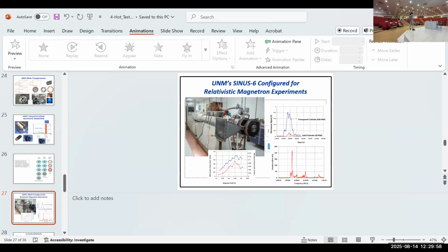I have a basic question. If we compare with other magnetron systems, they reach higher temperatures and higher power, am I right? These are low rate pulses, maybe 10 hertz, so you don't have much energy and you are not suffering from temperature. There is not much heat. You might need to cool it a little bit, but there is no heat problem because there is no average energy in this. There is no heated cathode. It's a cold cathode; we call it a plasma cathode. We are talking about peak power. Sometimes it's confusing, average power and peak power.